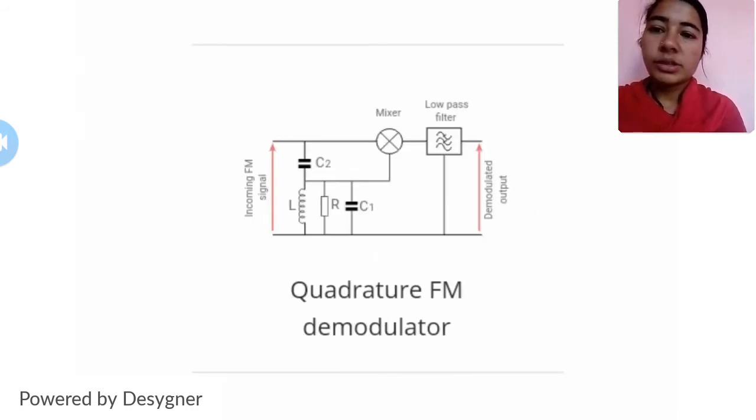The circuit of the quadrature demodulator. The two signals are then multiplied together in the analog multiplier device, which serves as a phase detector. That is a device whose output is proportional to the phase difference between the two signals. In case of an unmodulated FM signal, the phase detector output, after being filtered using a low pass filter, that is averaged over time, is zero.